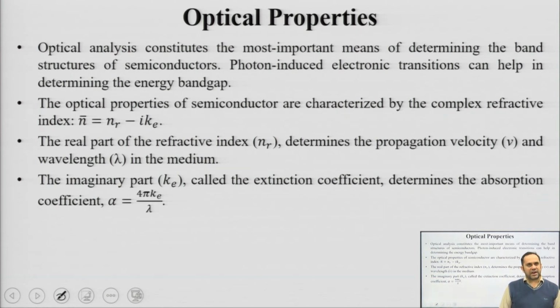They might get excited with this extra optical energy, and if this energy h nu is at least equal to the energy band gap, you are going to see a generation of charge carriers from the valence to the conduction band. Okay. And once they move back via recombination, if you measure the wavelength of the energy dissipated, it can help you to measure the energy band gap.